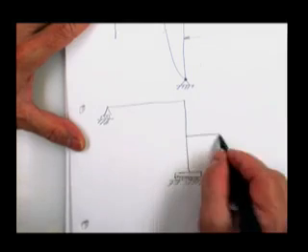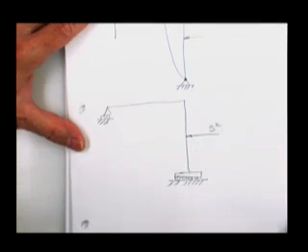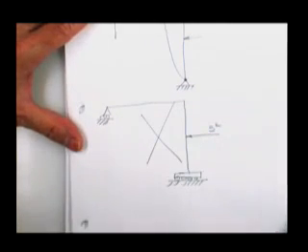That's not good. That one is one of the ones that won't work, because you have no place in the structure to have a horizontal resistance. Therefore, the whole thing slides down the road and it's not stable. So, no good for that choice of releasing this member.